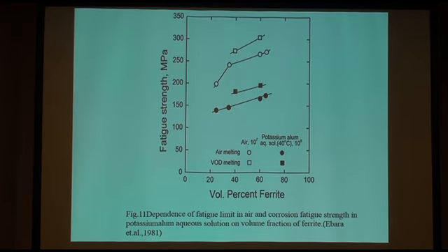So finally, I would like to talk about the microstructure effect. This is data for suction roll material. In the suction roll case, we had too many corrosion fatigue failures many years ago. Formerly we were using 13 chromium cast steel, but after that we changed to duplex stainless steel. This is very simple data, fatigue strength versus ferrite, around 40%. Then we tried air melted steel and vacuum melted steel, in an environment of white water at 40 degrees centigrade.